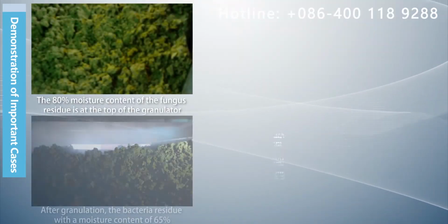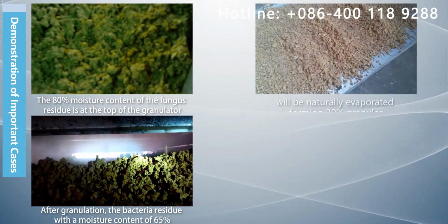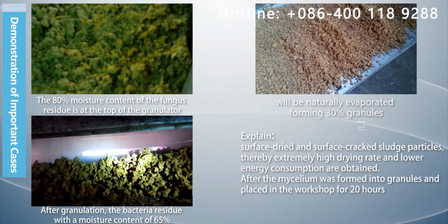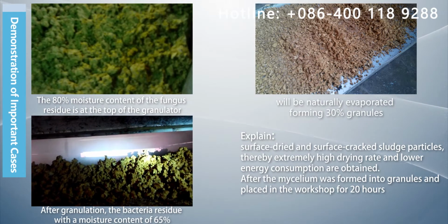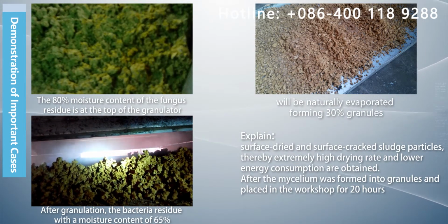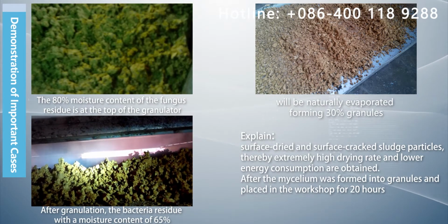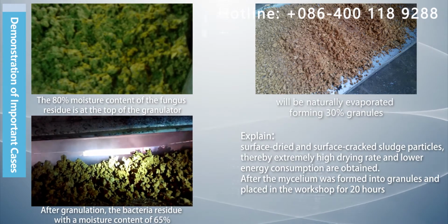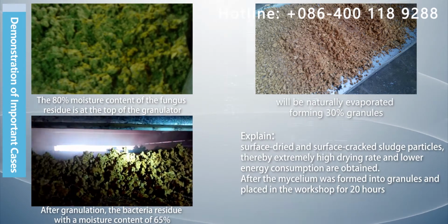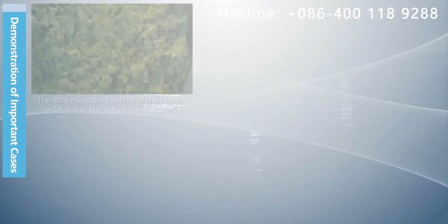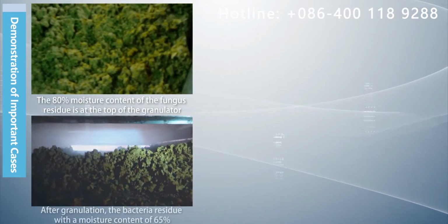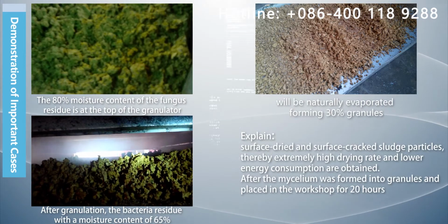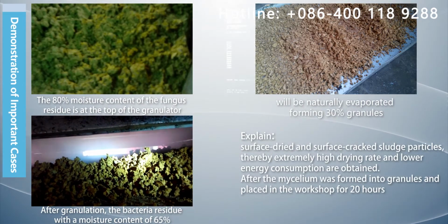The popcorn drying project. Another successful application case is drying 7-ACA mycelia with very high viscosity and water content for a big pharmaceutical company. The company conducted several failed experimental tests using traditional dryers. However, its sludge has been successfully dried by our exclusive granulation dryer. Our granulation process pulls its viscous sludge into fluffy particles, which causes the particle wall to break and dry to form porous, irregular, surface-dry sludge particles, resulting in the highest drying efficiency and lowest energy consumption.